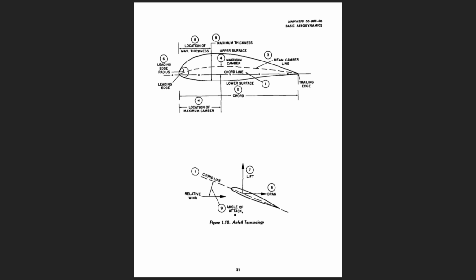Notice that the description of an airfoil profile is by dimensions which are fractions or percent of the basic chord dimension. Thus, when an airfoil profile is specified, a relative shape is described. Note: a numerical system of designating airfoil profiles, originated by the National Advisory Committee for Aeronautics, NACA, is used to describe the main geometric features and certain aerodynamic properties. NACA Report Number 824 will provide the detail of this system.